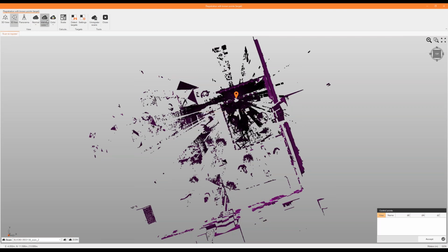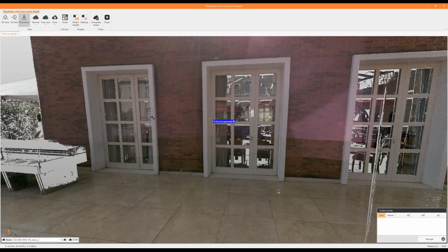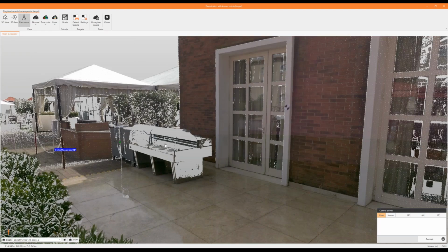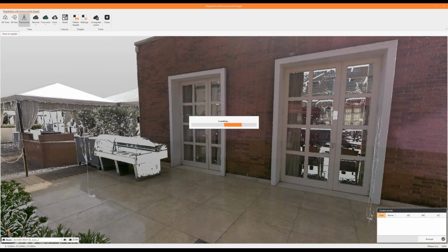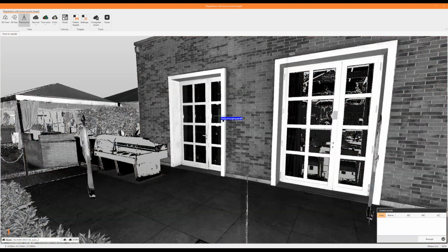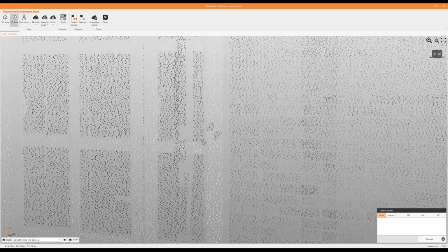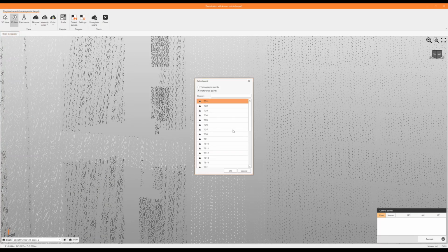Now, we don't know exactly the center of the scan. We can directly move to a different rendering visualization, panorama view, and here we can also find the other targets. Target number 2, this was target number 1, but of course we cannot correctly visualize it from this position. But we can directly select target number 2. Again, if you want to be sure that you are acquiring the point with the best position, we can also orbit in 3D, and this is the TS2.